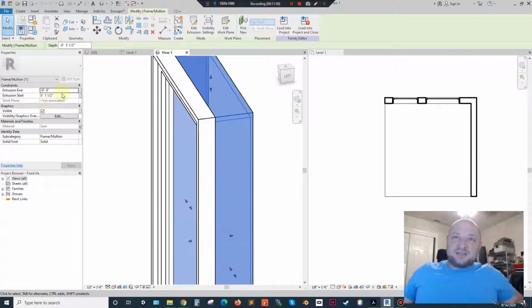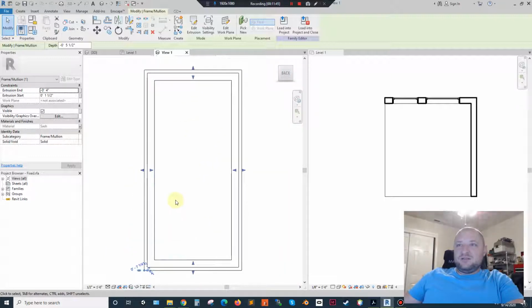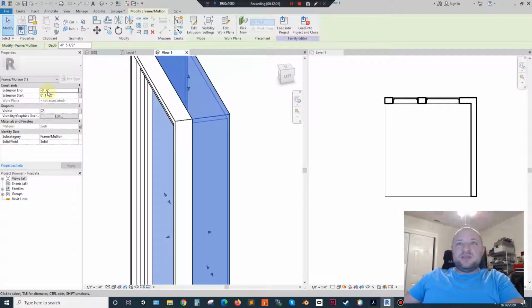And what this indicates is that this is an extrusion. It's using this direction. Like if we were looking at a map and that map was flat on a table, anything that came towards us was, in this case, minus, and anything that went away from us through that 2D map is plus. So right here we have an extrusion that starts at -4 inches, so 4 inches off that table, and then 1.5 inches, so it would go down 1.5 inches through the table.